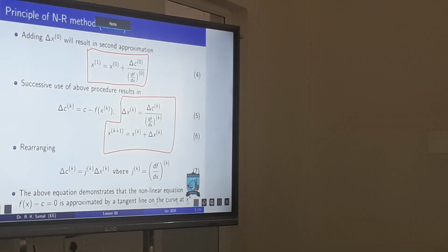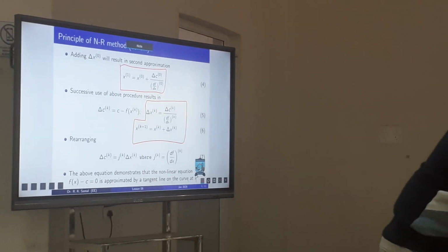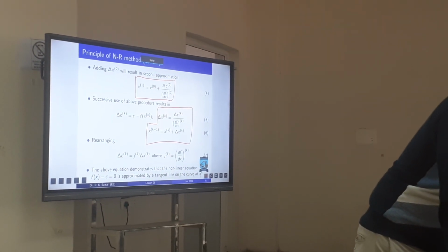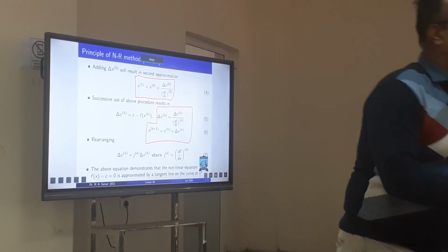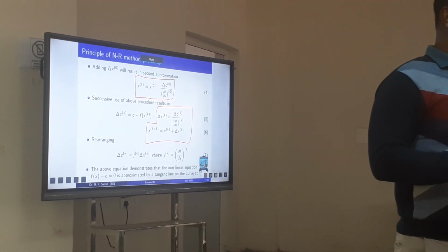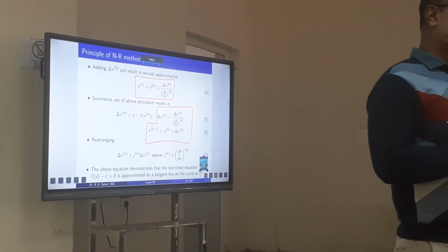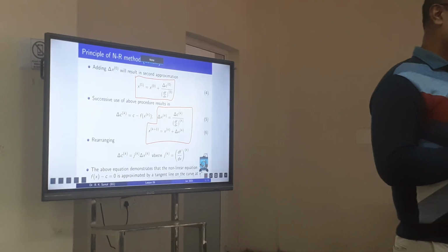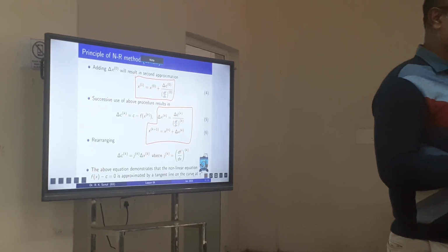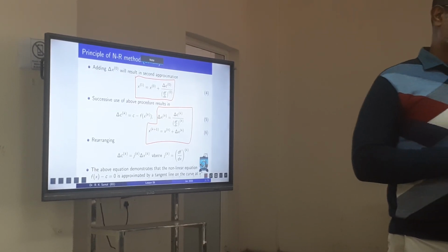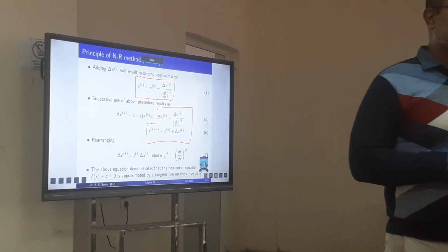What is f in our case? In our actual problem, what is f? What is our problem here? What are we trying to solve? Power flow equations. We are trying to solve the power flow equations. So what is f then? Complex algebraic load flow equations. So we have to find the derivative of the load flow equations. Okay, so it must be difficult. Therefore it can be done programmatically only. Manually it is possible only for small systems. The Gauss method did not require any kind of derivatives.